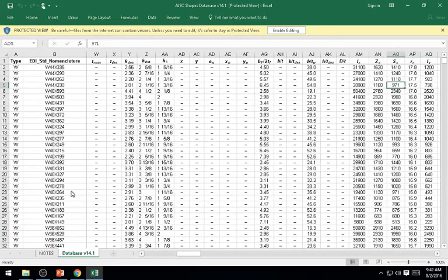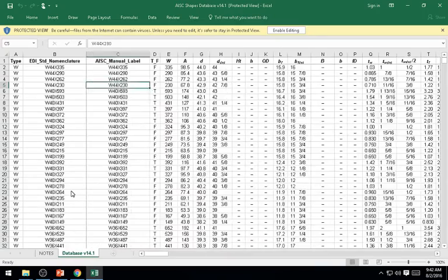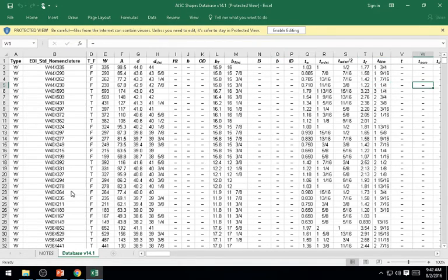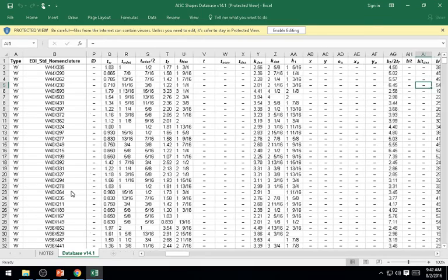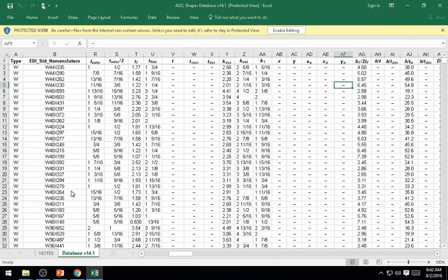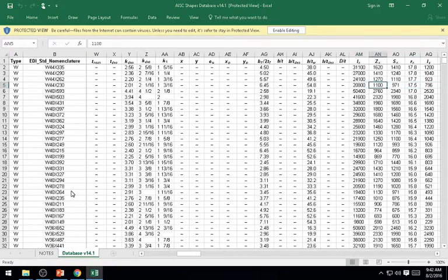And if you notice, they have all sorts of properties here. They have things like the weight, the cross-sectional area, the depth, a little bit different clarification on the depth, flange width, another measure of the flange width, thickness of the web. Some other properties I can't explain without getting too involved, another section property here, just the ratio of the beam to the thickness of the flange. That's useful for steel design.